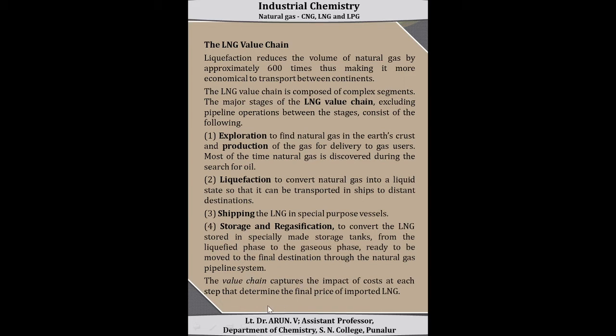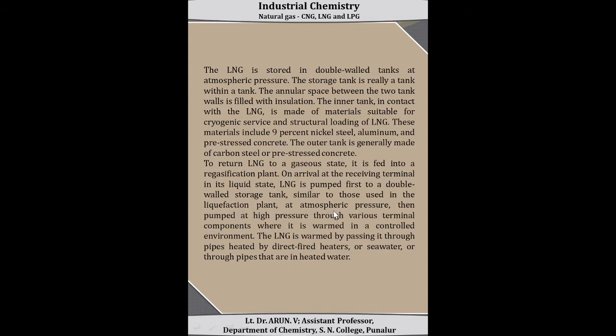This value chain captures the impact of the cost at each step that determines the final price of the imported liquefied natural gas. The LNG is stored in a double-walled tank at atmospheric pressure. The storage tank is really a tank within a tank. The annular space between the two tank walls is filled with insulation.